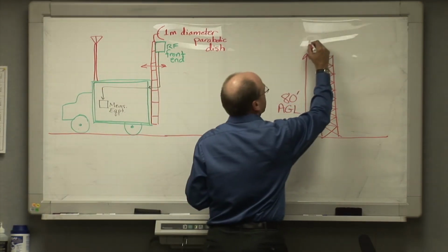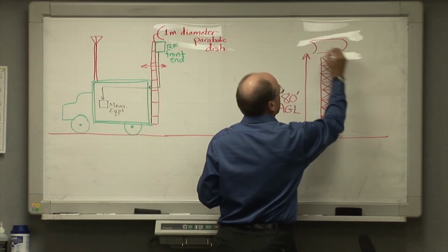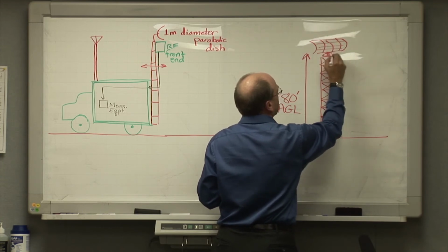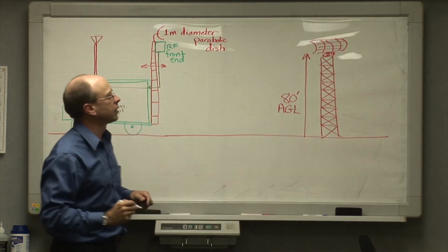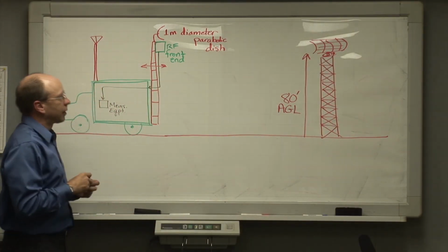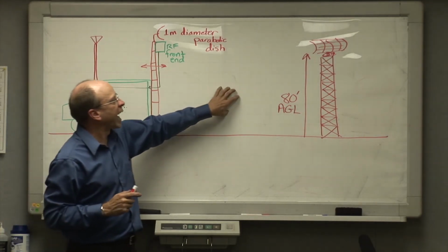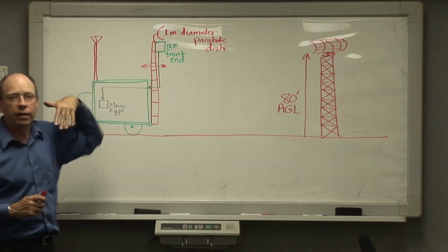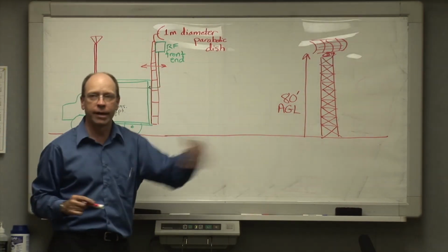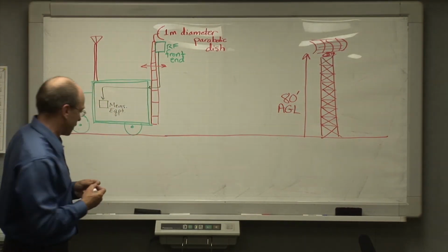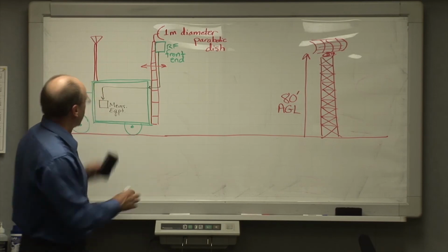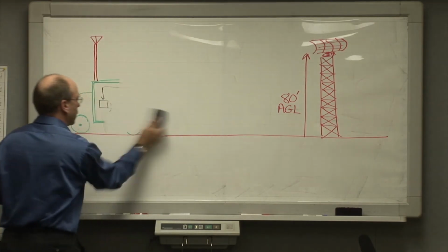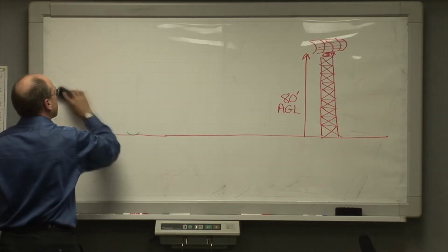They'll have a great big antenna mounted up here. And this antenna is mounted on a rotating joint. And you might think that the place where you're going to get the maximum amount of power out of this antenna would be at the closest possible distance from the radar. In fact, people commonly think that the closer you come into a radar, the more power you're going to get. But there's a problem. And to explicate the problem, I'm going to redraw the measurement system with the mast at something that's a little more appropriate in terms of height scale.